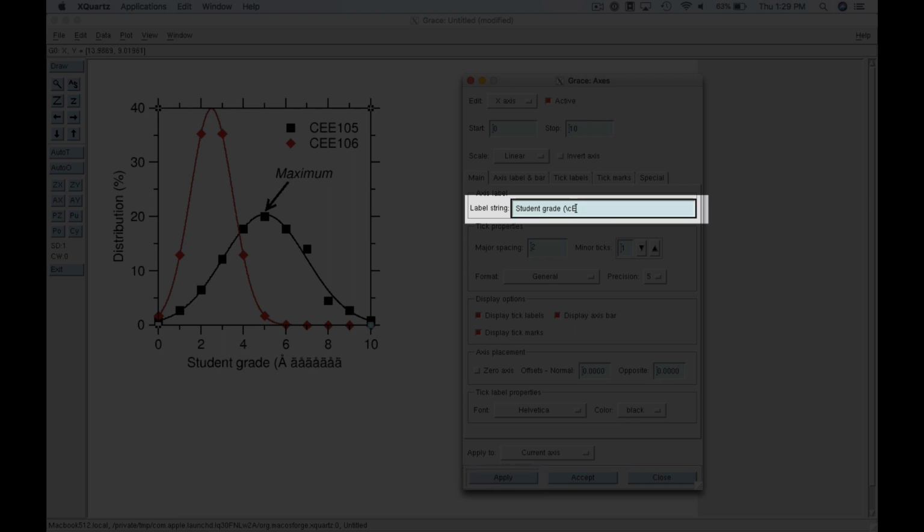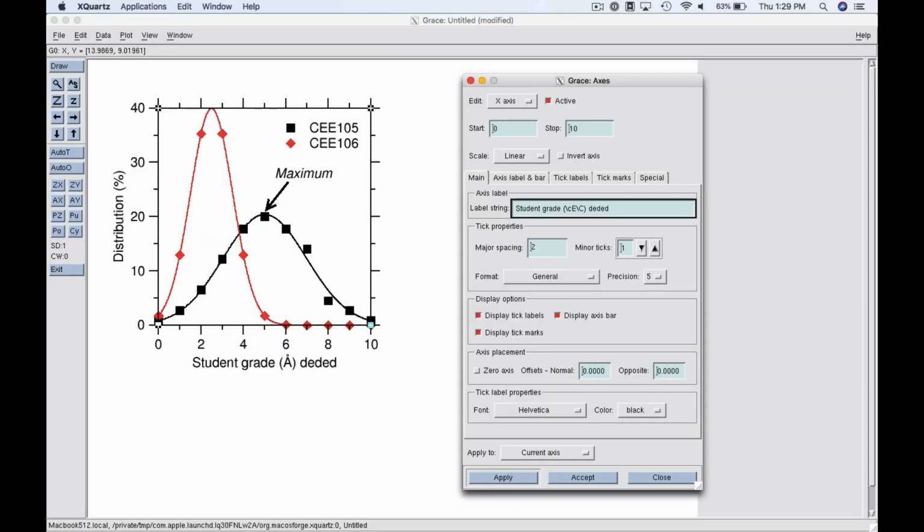So you would need to exit the special character mode by a /C, and then you can go back to write some default text. Okay, so those are not easy features of XMGrace, but you just need to remember those basic things about how to do a superscript, how to do a subscript, how to do a special character, etc. And then you don't need to remember this all the time.